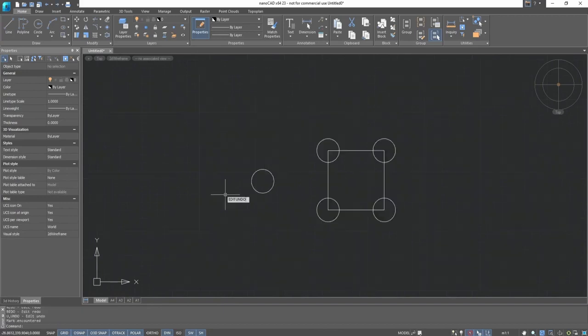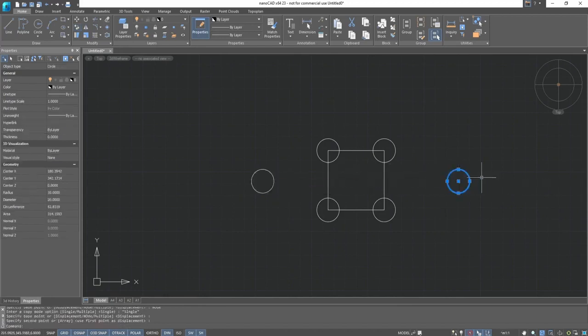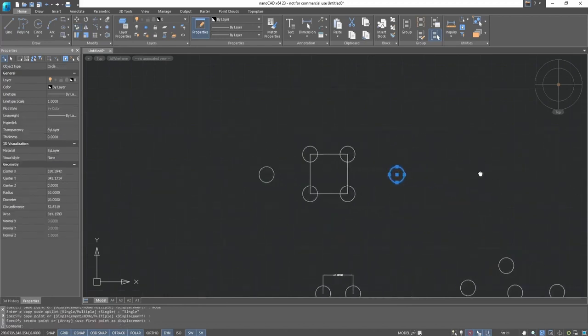We'll call the Move Copy command, select the object, and then move to the mode option. This option suggests copying in a single mode, or multiple objects for copying. We can use the single mode and see what it entails. We see that the copying does not continue. This is convenient if you need to copy an object only once.